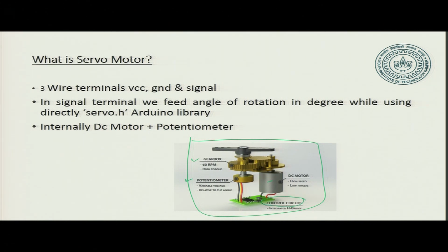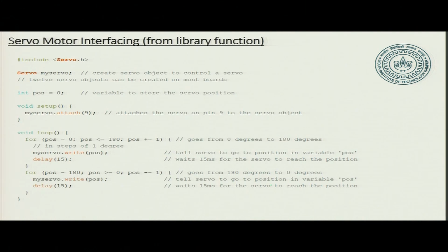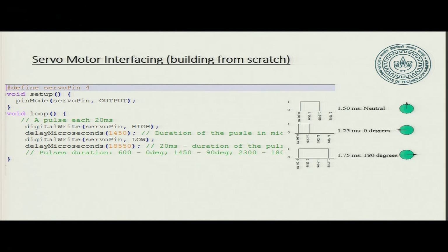So, there is a PID kind of a controller here, okay, and this is calibrated. So, what do I mean by calibrated is that the potentiometer is calibrated to move this from 0 degrees to 180 degrees, okay, or from 0 degrees to 270 degrees. Okay. So, it is pre-calibrated from before. So, what it basically means is that I can give a particular voltage. So, let us look here. So, this is my calibration that is normally there.